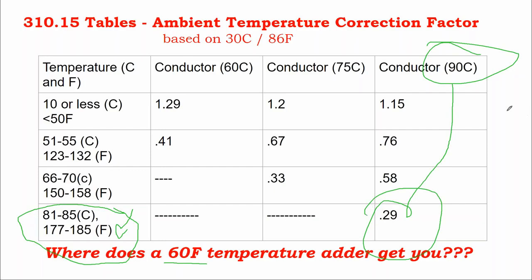But actually, this isn't so bad, because it's not just ampacity sizing in cables. It's the friction of the electrons as they're flowing through the cable jacket itself that results in losses called voltage drop. So you often upsize solar cables anyways because of voltage drop.